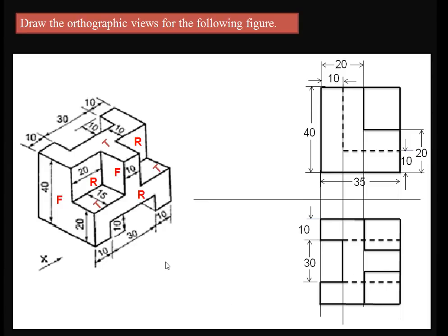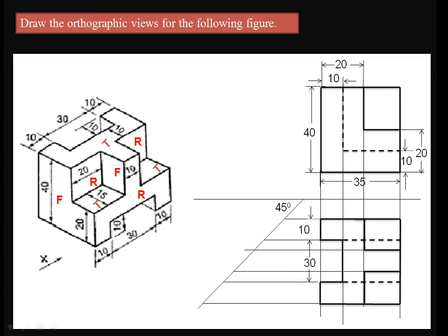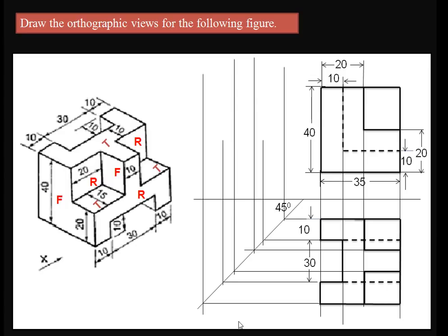So next we go for right side view. For that, draw a line at a particular distance from the two projections we have drawn with an angle of 45 degrees. So after drawing this line, draw the projection lines like this. Now from each and every edge we need to draw the projection lines until they intersect the line which is drawn at an angle of 45 degrees. So from these intersecting points, again draw the vertical lines for getting the final right side view. So in this I want to draw first again projection lines from the front view also. Drawing the projection lines from top view, drawing the projection lines from front view, we will be getting certain intersecting points. So by using these intersecting points directly we can draw the right side view.